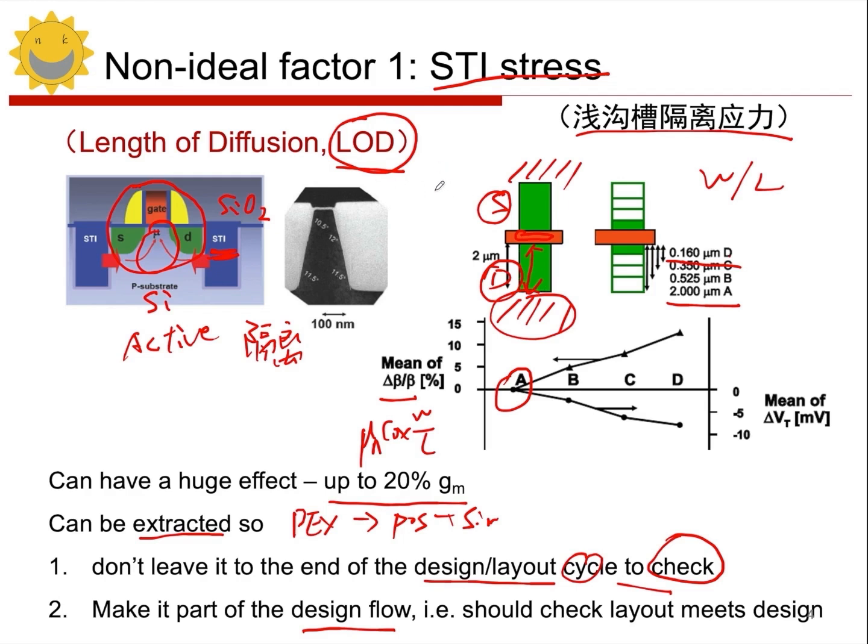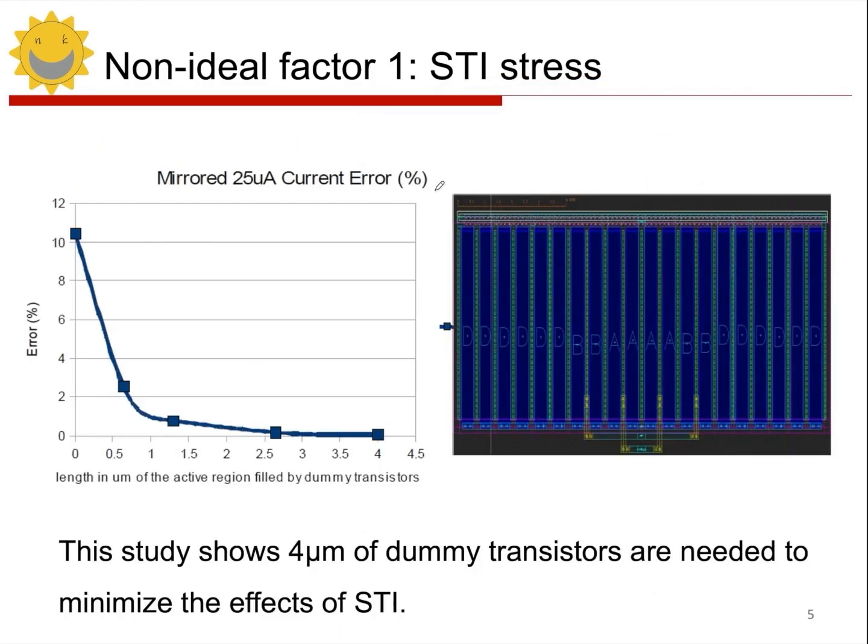So this issue is the first one, the non-ideal problem. As we mentioned earlier, the stress in STI is influenced by distance, right? The distance from our drain area to the channel. The farther its edge is from the channel, the farther our STI will be from the channel area. In this way, the stress of STI is reduced.